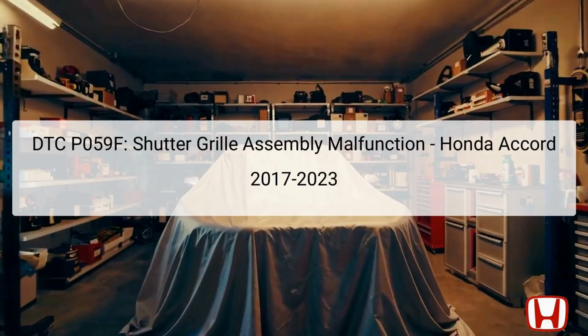The DTC P059F indicates a malfunction in the shutter grille assembly of the Honda Accord from 2017 to 2023. The shutter grille plays a crucial role in managing airflow to the engine and improving engine efficiency and aerodynamics by opening and closing its slats based on temperature and speed. Located at the front of the vehicle, the assembly involves multiple components, including the actuator that adjusts its position.